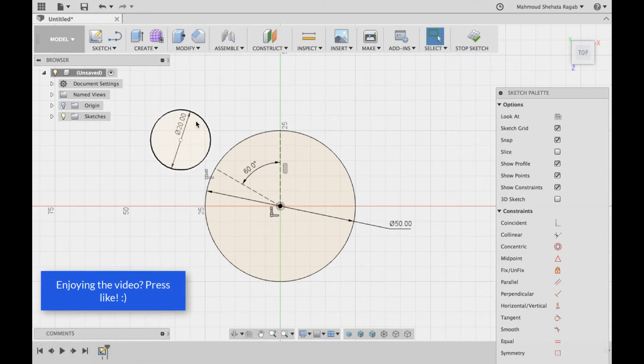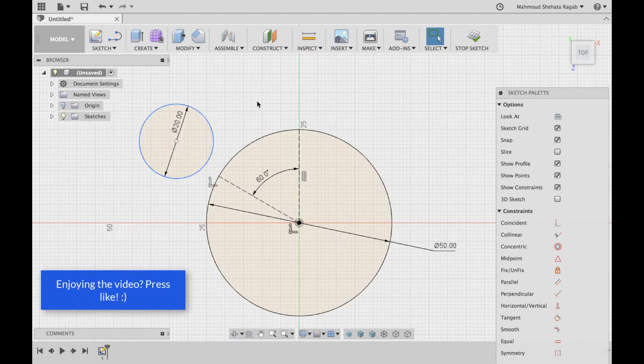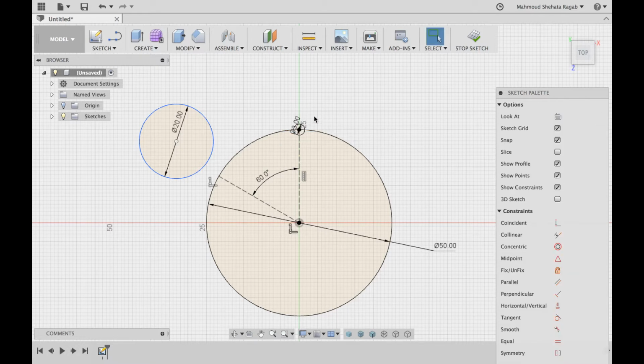Now let's turn our attention a little bit to the drive wheel. The drive wheel has some sort of a locking ring that's going to be cut out of this circle, and it's also going to carry the drive pin. Now the drive pin is going to be somewhere on the center of the slot by definition, because it's going to slide inside the slot. So let's put it somewhere here. 3 millimeter in diameter will do, so that's nice.